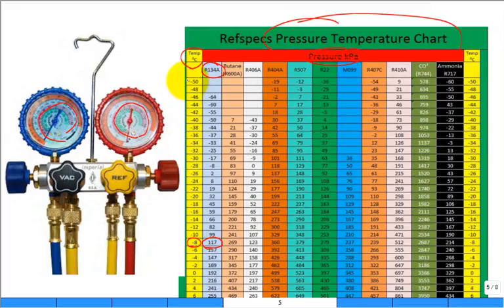Somebody says, what is the pressure of the refrigerant in this can right now? Could you even come close to a guess of the pressure of the refrigerant in this can? It's a pure 134A. You have all the tools to tell you that, right? And you take this can, and they say, don't set it in direct sunlight. Why? It'll get a lot hotter, and the pressure, will it stay the same, or will the pressure go up?